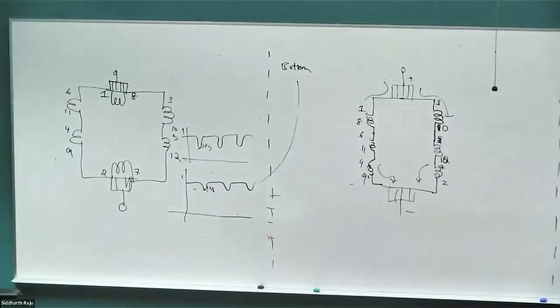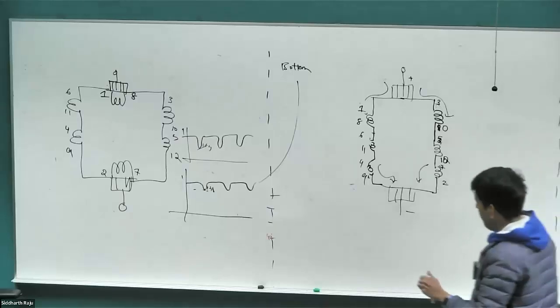There is another problem when we break this contact. When we moved from 1 to 2, there was current previously in this conductor. Now the conductor current is breaking and moving to C2. Right? We are still interrupting a current. That would be a problem. So with that commutation, we need to ensure that the current completely transfers from one direction to the other when the breaking happens, which we will do when we meet